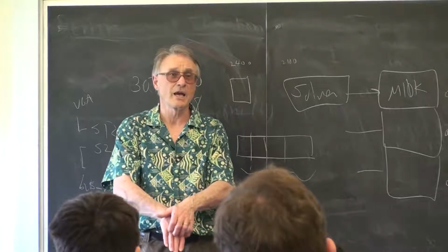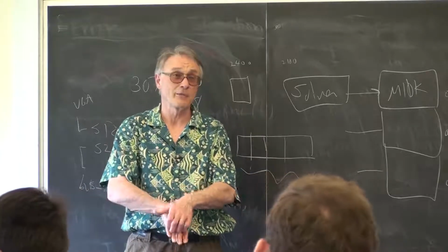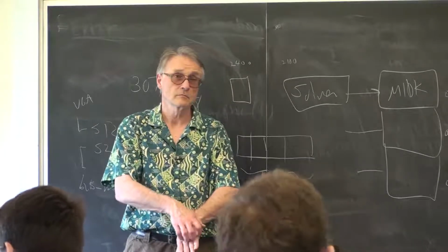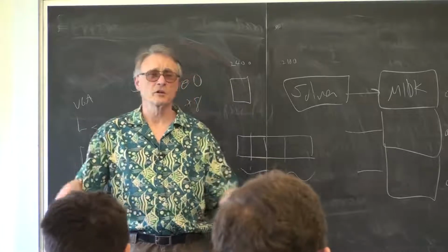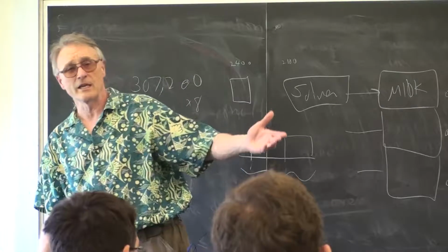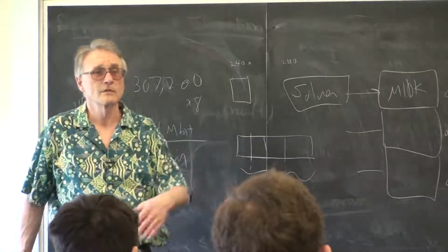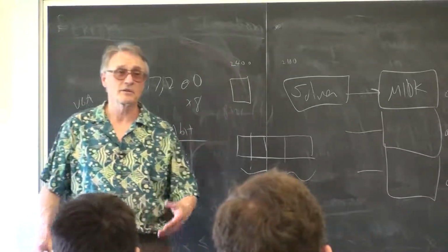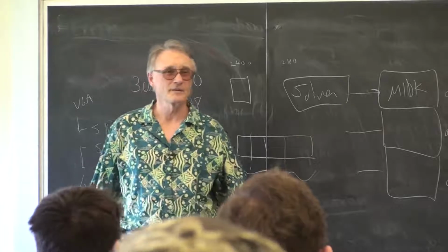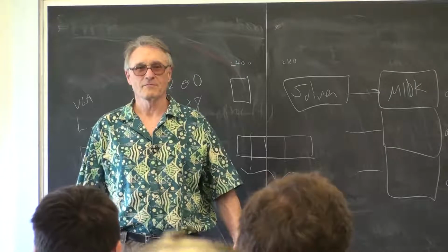You could also run those through the I/O pins. You could run a logic analyzer through the I/O pins and get much better bandwidth that way. You do a mixed oscilloscope: use the digital I/O pins for 16 digital inputs, and use the A to D converter for 2 or 4 analog waveforms. That'd be cool. Oh, and also throw in a synthesizer there so you could make a signal generator. Then you have your lab on an FPGA with data logging to the HPS.